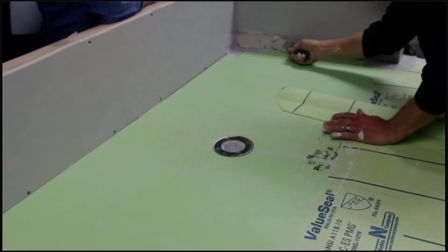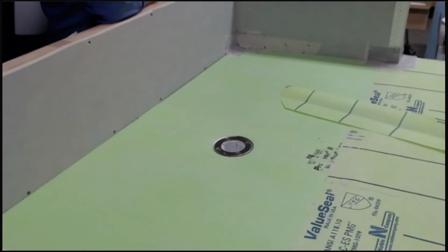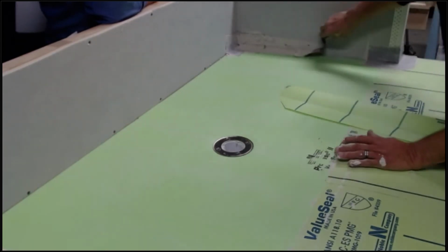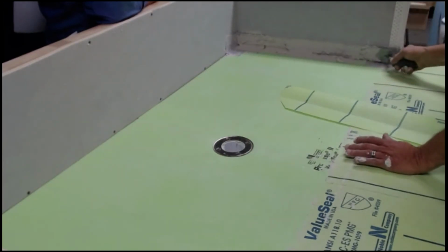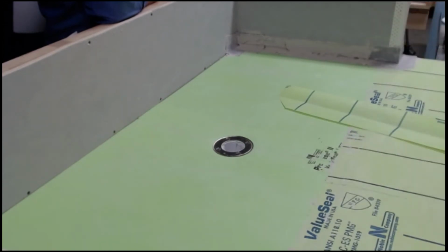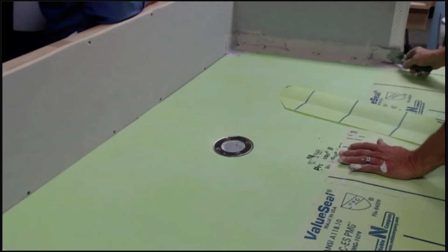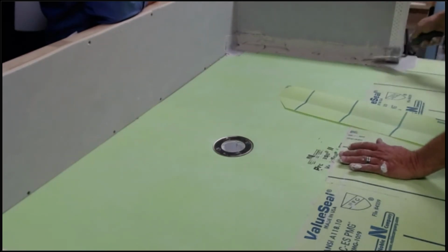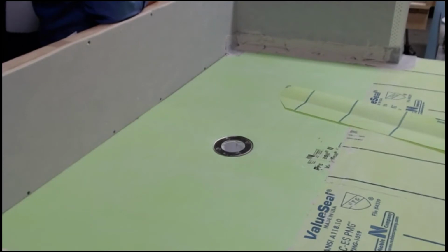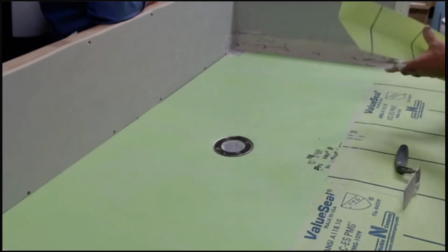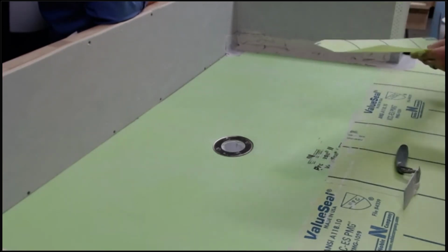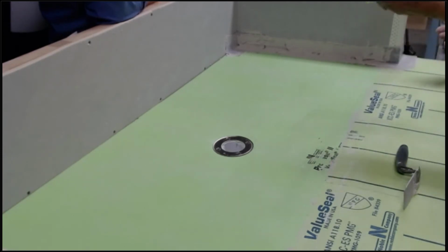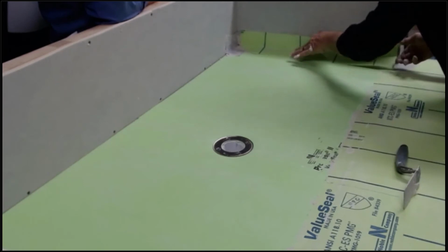So for the cap strip, we're just going to put a layer of thin set on. I'm looking at your cap strip. That's a product that the Noble Company sells, five inches wide, and it comes on a roll. You could cut off a big piece if you wanted to. Now I'll fold the cap strip since Value Seal holds the fold. It's a little easier to fold it. Give it a nice tight 90 in there.